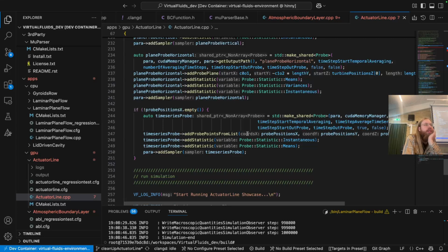But the velocity is 0, and your stresses are not going to... Well, that's the thing. The problem is that you have a very high gradient between the wall and the node. You can't set the velocity, which the solver basically doesn't see. You have very high viscosity, a lot of very small scale turbulence near the wall. Between the wall and the first node, you have so much turbulence that affects the flow that you don't see in the simulation, but we know that's the result we want to see.